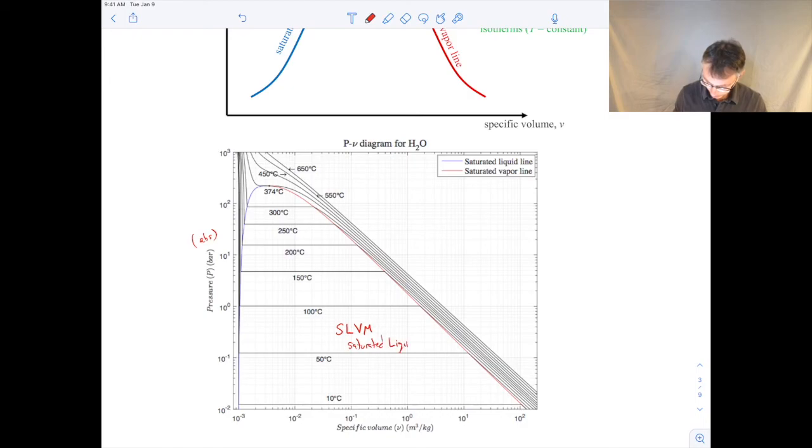Over here is vapor, and over here in this smashed in region is the liquid. Okay? The critical point is right there. I'll just abbreviate it as CP. And there are certain features on here I'm going to identify. This line that goes from the critical point down and separates the liquid vapor mixture region. So in this region here, we call this the vapor dome.